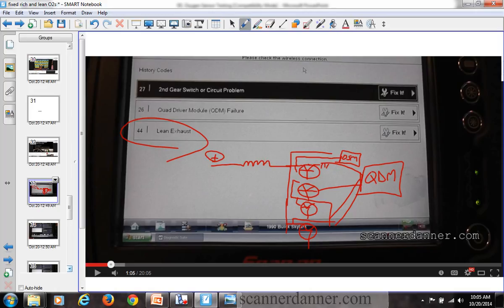What is that? It's nothing special. It was an old GM. I remember when these first came out, people were like, quad driver, these computers are crazy now. It's just an output state monitor is all it is. A QDM fault on this car means one of those 4 outputs has an open or short. So then you get a diagram and you figure out which outputs are on that particular QDM. It's no different than today's cars when you have an open or shorted solenoid. How's the computer know that? It monitors it. Cool? See, that was like 30 seconds, wasn't it? And if you have any questions on that, too bad, wrong topic. Go back to section 3 if you want to learn more about output state monitors. Let's keep going.